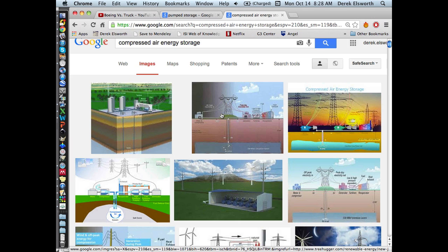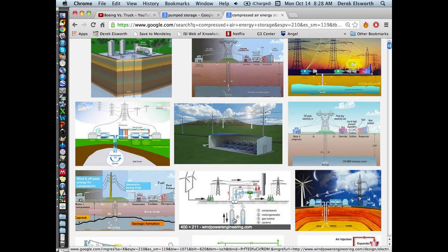And so instead of taking it up to an elevation and then dropping water down with its mass, you actually store the potential energy, if you like, in the elasticity, the compressibility of the gas, either in caverns, which is sometimes the case. In northern Pennsylvania, for instance, there are all these gas caverns which are in salt. You put a cased hole down, and you just circulate water around the bottom to dissolve out the salt. You retract the casing, so you get these big, long, cigar-shaped holes. They might be tens of meters in diameter and hundreds or thousands of feet, certainly hundreds of meters in height.